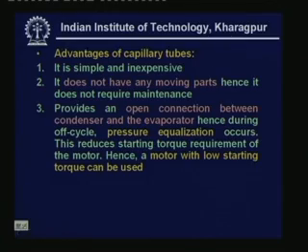When the system is off, that means when the compressor is not running, the condenser pressure is much higher than the evaporator pressure. So, pressure equalization takes place through the capillary tube, because the capillary tube is nothing but an open tube. So, finally during the off condition, if sufficient time is allowed, the entire system pressure will be the same. So, when the compressor starts after the off condition, it does not have to start against a high back pressure. That means it does not require a lot of starting torque to start, so you can use low starting torque motors.